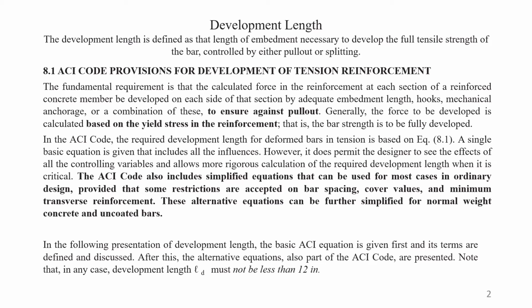In the design of concrete structures, naturally we like the steel to fail in any case, because steel fails gradually and concrete fails suddenly. Here also we will see that the steel comes out and elongates. If it elongates, then it shows that the steel is failing, and then we can take some precaution for the structures. Now we will go to the formula directly on the next page.